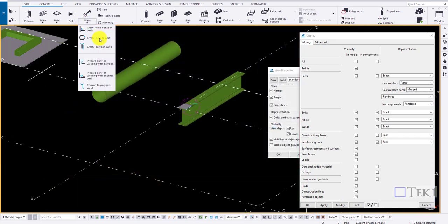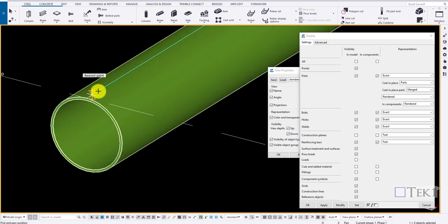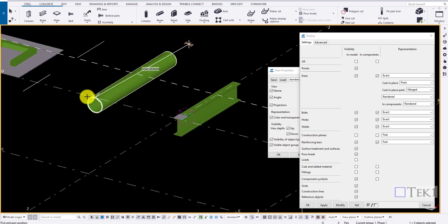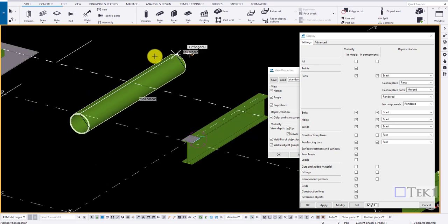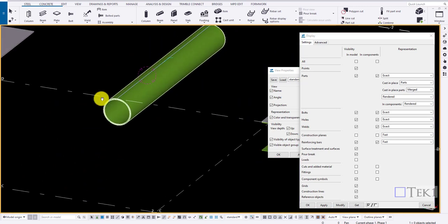Now let us look into the weld to part option. Folded sheets are turned into SHS profile and the weld is created. Choose the weld, draw the line and click on the middlemost button to apply the weld.